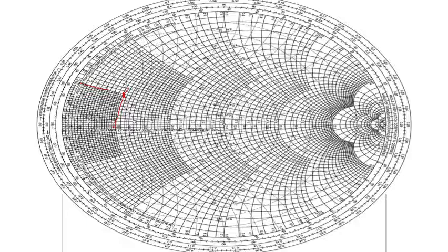Now how do we start with the lumped element matching? In lumped element matching, we have to find out along which circle we are supposed to move, one, and secondly, till where we are supposed to move. In this entire lumped element matching, we are very clear that we are not on the unity gain circle. Meaning, the unity gain circle lies on the right hand side.